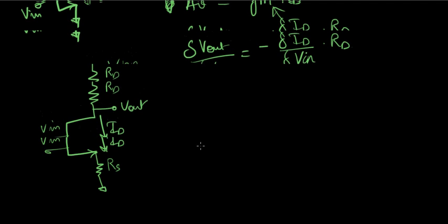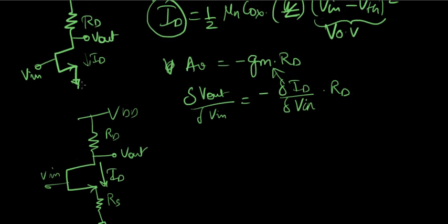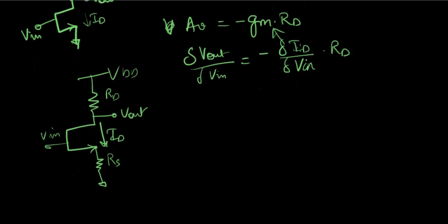So when you compare these two circuits, the top one and the bottom one, I always say that the gain equation has the GM, the transconductance of the input part, times the load resistance as viewed from the output node, right? Now in this circuit, the load resistance remains the same, RD, but here you have a different input structure. So GM would be different here, and it would be called capital GM.